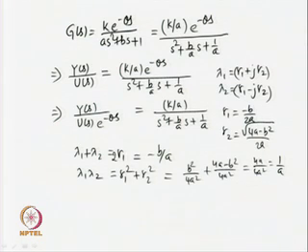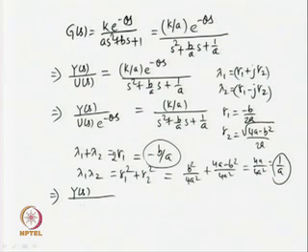So, I can write the denominator now in the form of either b by a or 1 by a, or I mean now the same expression can be rewritten as y(s) upon u(s) times e to the power minus theta s is equal to k times lambda 1 lambda 2 in the numerator. Please keep in mind 1 upon a is equal to lambda 1 lambda 2.